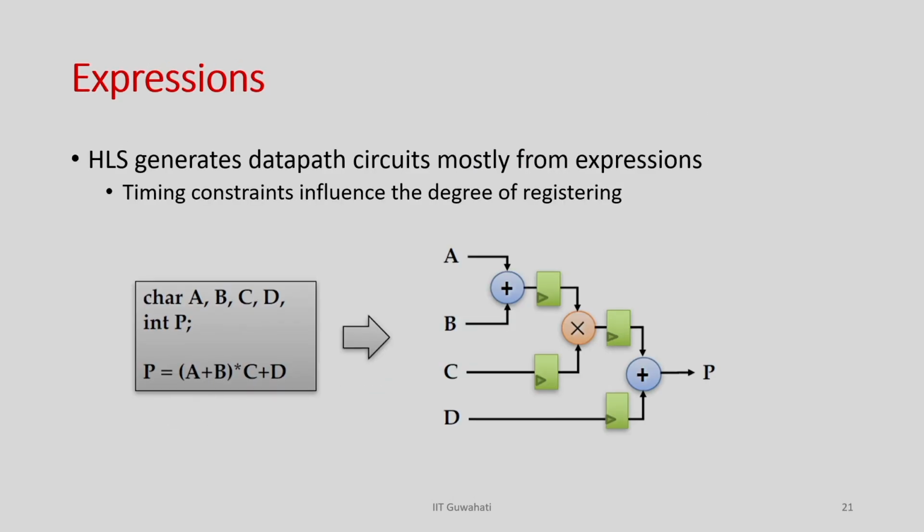And the expression, I have already explained, will map to these function units, and usually the expression gets split into three-address form that I have already discussed, and then it gets scheduled, right. So, it is not that the whole expression is going to execute in one clock. Based on the target clock period, you might try to execute this in multiple cycles, which I have already discussed.